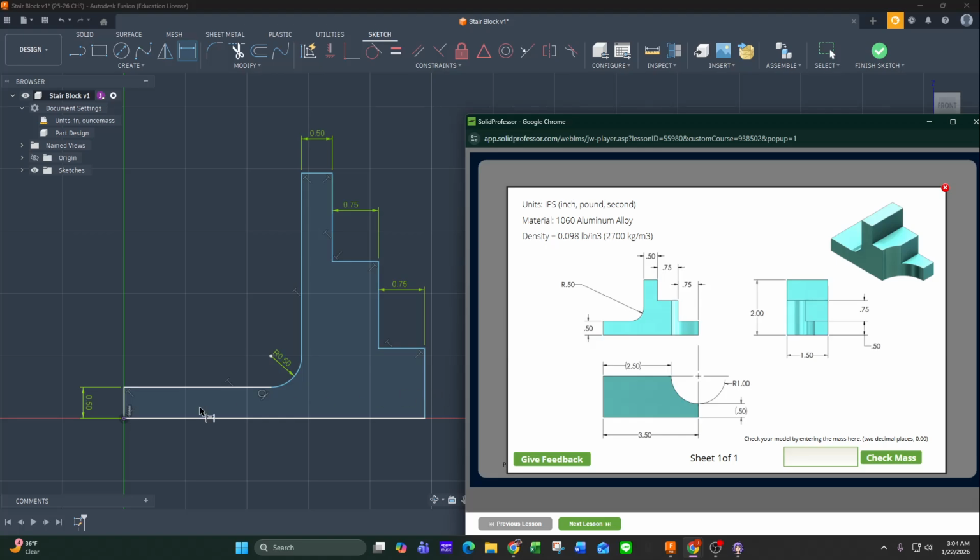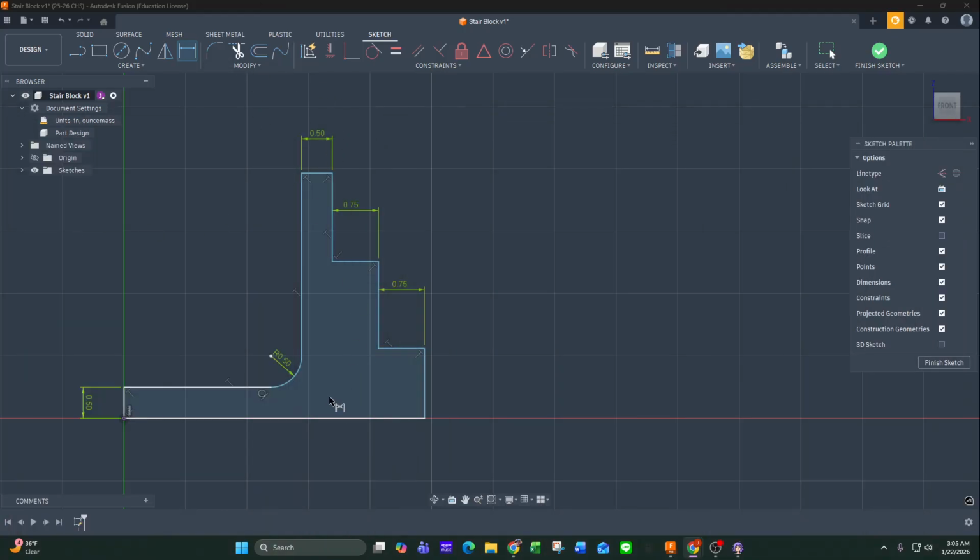You'll notice it does not bother us with the overall. At this point, we'll pick that up from over here. But again, at this point, we're kind of good with this front angle. This is all depth information. We do have a height here. So the overall height from the bottom to the very top, you can see that right here, is 2 inches. So I'm going to scoot this over. Dimension, so left click on the bottom, left click on the very top, move this out to the side, 2 inches.